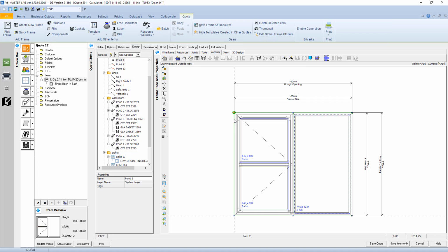What that means is, if you run the grid frame wizard, for example, if you add a new frame on the fly to the code, then run the grid frame wizard and say it's going to be 2 by 2, and you have some joint formula to be calculated automatically, that will work the same way as in pre-configured frames. So the system will check the frame type and will bring all the formulas and attach them to the points that are relevant.